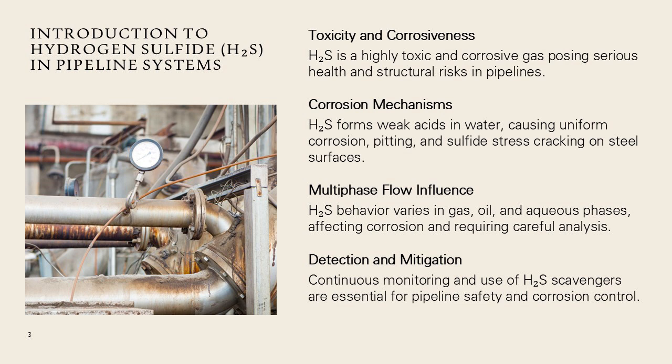When H₂S dissolves in water, it forms weak acids that aggressively attack carbon-steel surfaces, resulting in uniform corrosion, pitting, and sulfide stress cracking. This degradation can compromise pipeline integrity, leading to leaks, ruptures, safety hazards, and costly downtime.